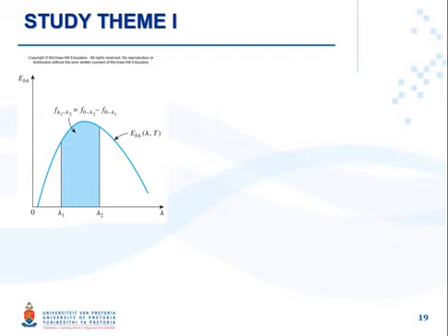So we just finished speaking about the Stefan Boltzmann law. To get to Stefan Boltzmann, we integrated for all the wavelength. But sometimes it's necessary to know the fraction of the total emission from a black body that is in certain wavelength intervals. So we are not interested in all the wavelength, we are just interested in a specific wavelength.